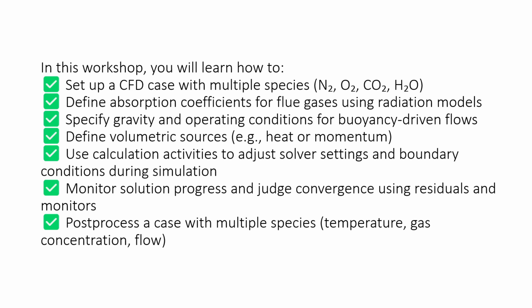How to monitor the solution and judge convergence using residuals and surface monitors, ensuring your results are reliable. And finally, how to post-process a case with multiple species, visualize temperature, gas concentration, and airflow to understand how the fire spreads and how ventilation impacts safety. If you're ready to boost your CFD skills and tackle challenging fire simulation problems, you're in the right place.